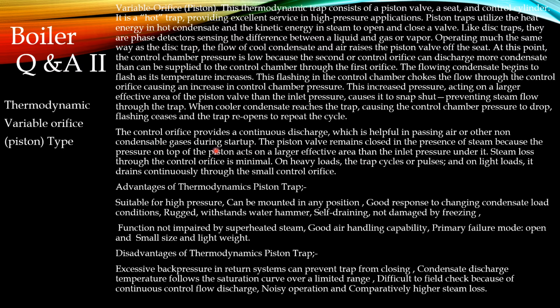The piston also works the same way. Advantages of thermodynamic piston traps: they are suitable for high pressure and can be mounted in any position, whether vertical or horizontal. They have good response to changing condensate load conditions. They are rugged, withstand water hammering, are self-draining, and will not get damaged by freezing.